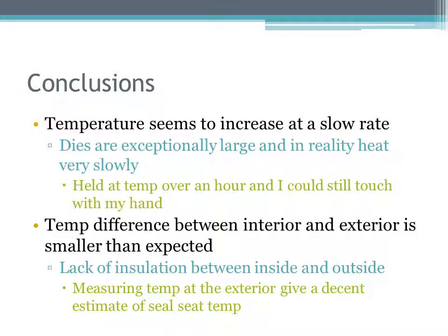In conclusion, the temperature seems to increase at a very slow rate. Dies are exceptionally large and have the capacity to absorb a lot of heat, so we have to keep that in mind. The temperature difference between the interior and the exterior is also much smaller than expected, so perhaps a good way to estimate the temperature of the seal seat is simply by measuring the temperature of the exterior.